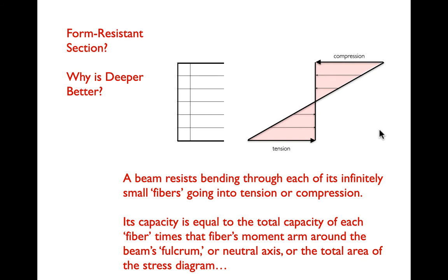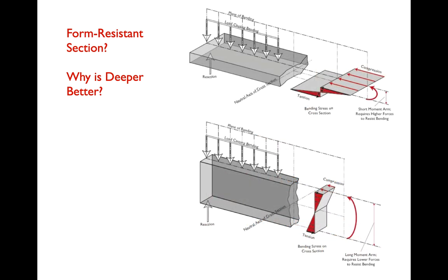Okay, we would like to not do this with calculus. We will come around to a way to do this. The key thing here to look at, though, is that the farther away we get from the center of the beam, what we'll call the neutral axis, the farther away we get, the greater the stress. And remember that the total capacity of the beam is basically those areas. So already we have a way to talk about the relationship of depth to strength.